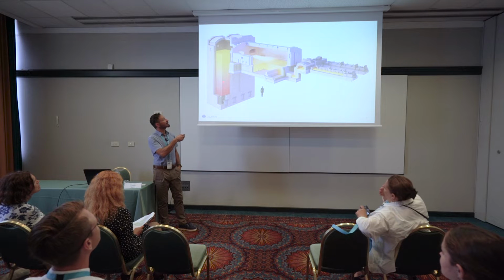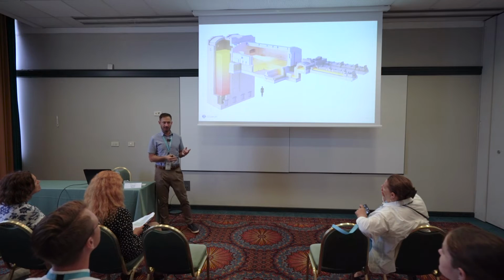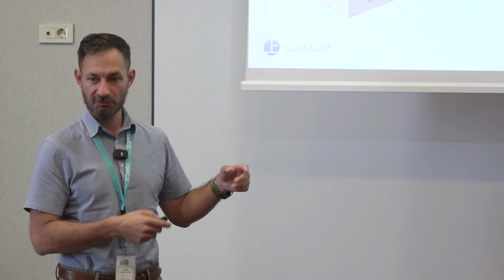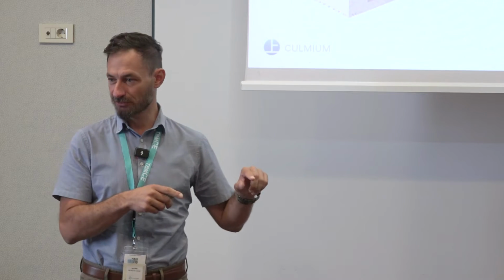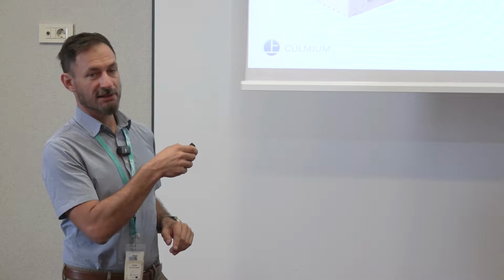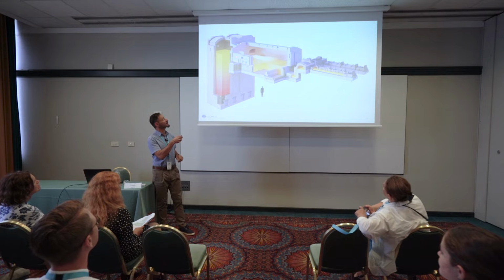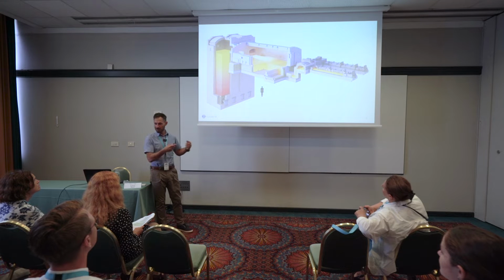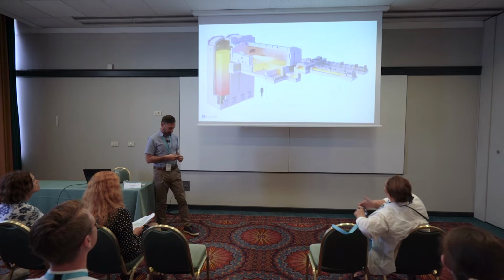Here in the back we have two such pillars that are used to harness the energy of the heated up gases, and this is used for preheating the gases that go into the furnace. We see this is one exhaust pipe. Behind here is another one, and these are the burners. The side of burning is changed every 20 minutes, so this is to capture this energy.